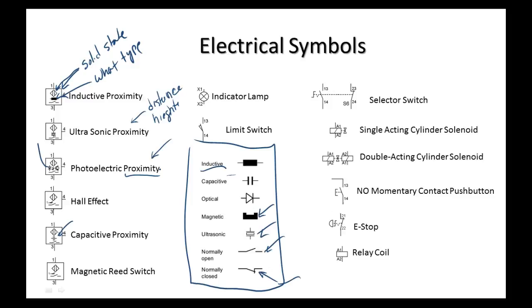So a proximity switch means these guys are looking for parts to be at a spot. So that 1B1 is looking for a part to be sitting right there on top of it, right? You understand that B1. If the part wasn't there, it says it's not there. So what is the Hall effect? A Hall effect sensor senses a magnetic field, but it's solid state.